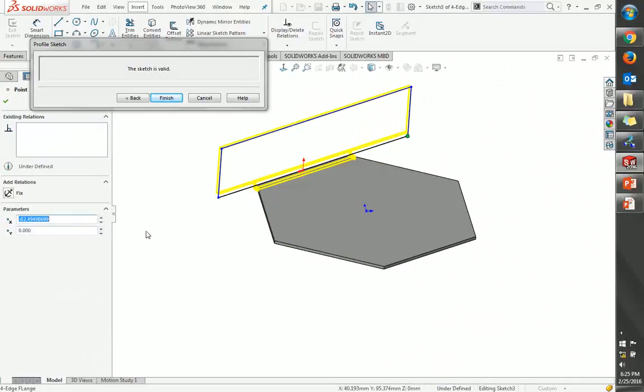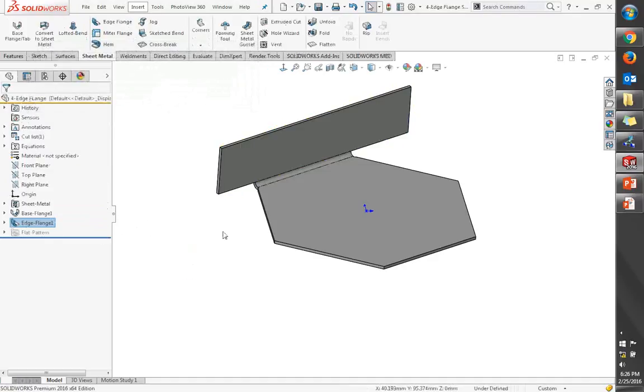Usually what happens is if you had to get a bigger flange, you had to make a small flange, then you had to add tabs to the end, a couple of sketches, a couple of features. Now we don't have to do that stuff. So I think this is actually one of those small little things that's actually really huge, because basically we've always had to work around the limitation before. In fact, when I saw it, I actually had to go back into 2015 because I'm like, you can do that, and I'm like, wow, it actually fails out. It doesn't even work. So keep that in mind. It's one of the tools that we've added to make life a little bit easier. And if you work with sheet metal, these might be conditions that you may have to get into. So keep that in mind.